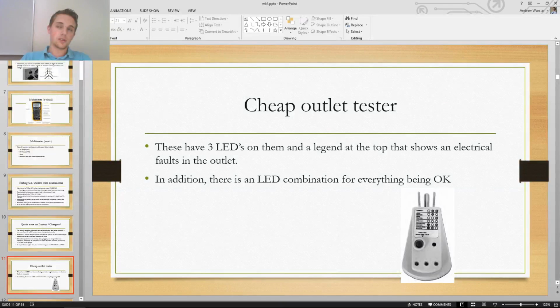But if you have really sensitive electronics and you keep having sags or spikes, it might be sensitive against that. So what we need is surge suppressors or UPSs. UPSs can have surge suppressors built into them, and they usually do. Large sags are known as brownouts, and complete power loss is blackouts. Pretty easy. The lights go out and it's black.